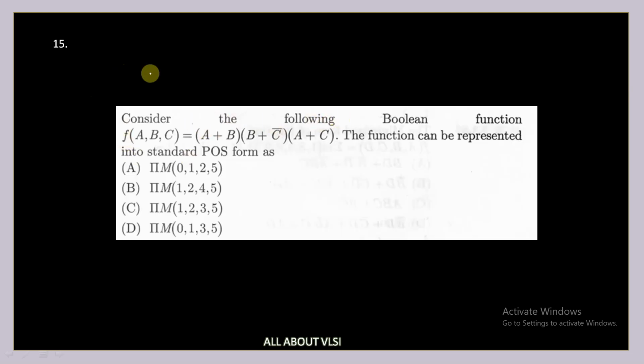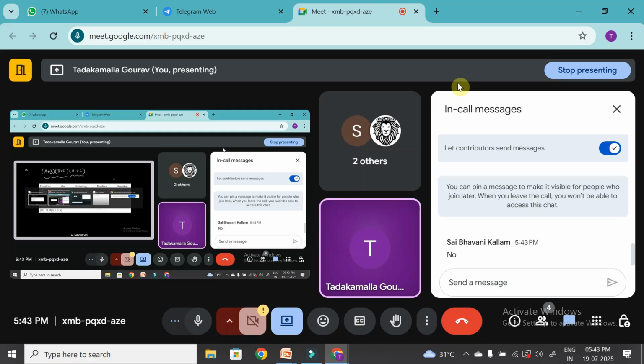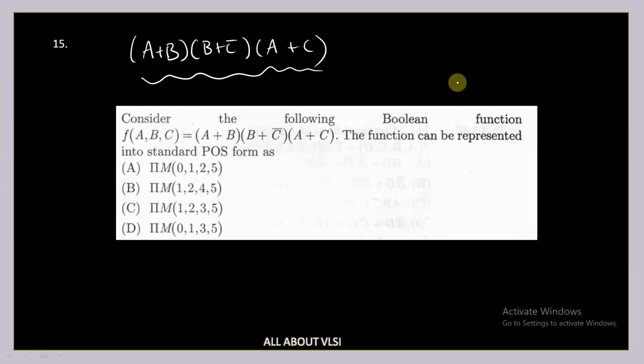So this one also, okay, try this one: (a + b)(b + c')(a + c). They're asking for the max terms. So can we take the max terms directly from this function? No, we cannot, because it is not in a standard form.